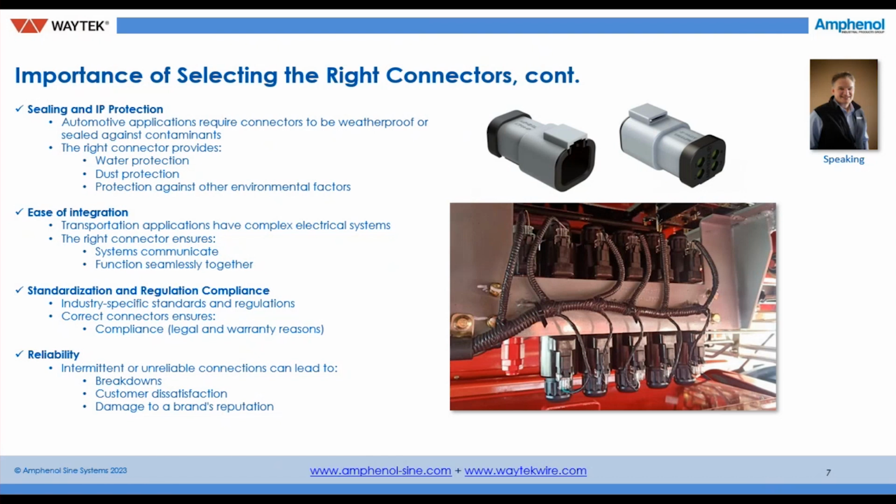When you think of these silicone seals and how they protect from water ingress to the back, they work great. But if they're in an environment where you have petroleum-based products, they tend to expand, or they may even expand to the point where they potentially dislodge from the housing. So an added feature would be an end cap, like you see there at the top of those pictures.